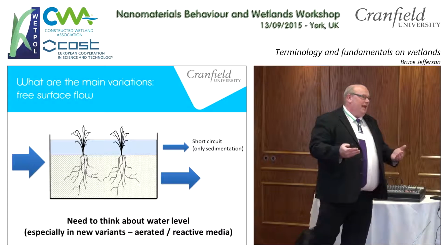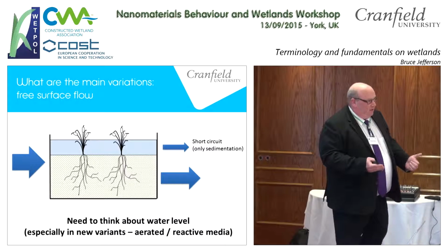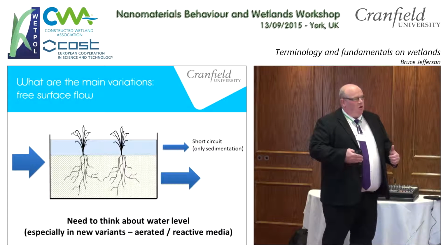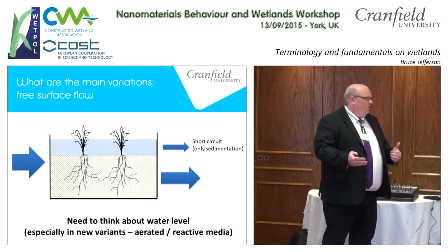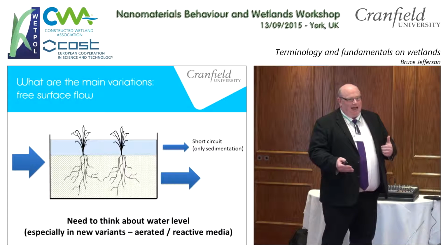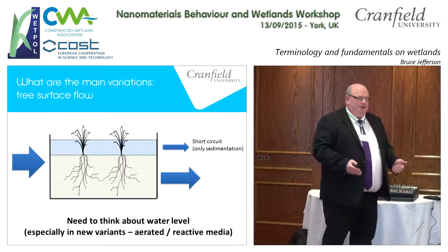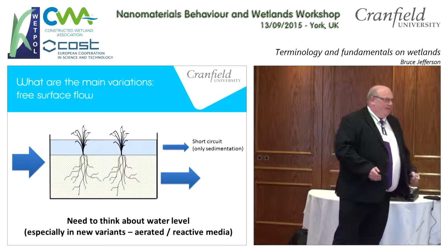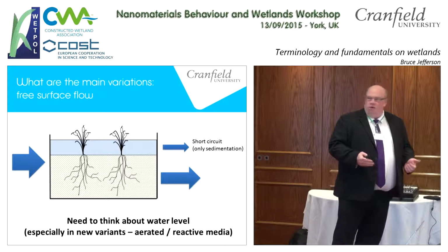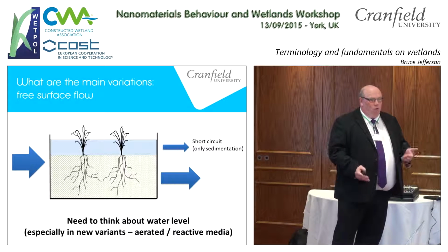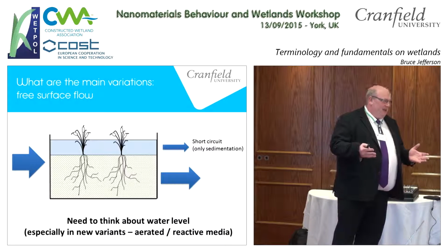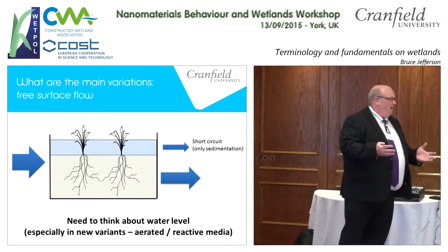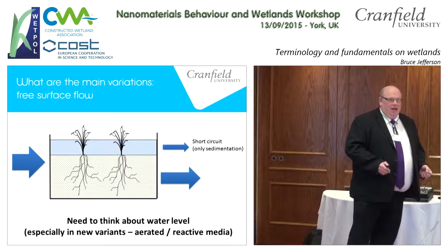So we do a lot of work, me and Gabby, for the UK water companies on treatment wetlands. So that's really where I'm coming from. Now, most of those are horizontal subsurface flow. So they're there to capture solids, remove some organics, denitrify a bit, although no one's putting them in for denitrification consents. So they're really there for solids. As a consequence, it's not been so critical about water level. They're there for sedimentation. A little bit of water above the media at such a slow rate isn't going to really distort the bed.